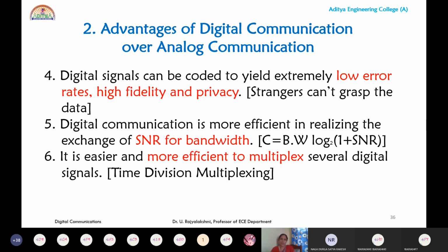Similarly, user 2 is given the second band for the whole time, user 3 the third band, user 4 and so on. The input signals are divided and given individual frequency bands. Frequency is divided, but applied for the whole time interval. All analog communication techniques utilize analog modulation, especially frequency division multiplexing as a transmission technique.